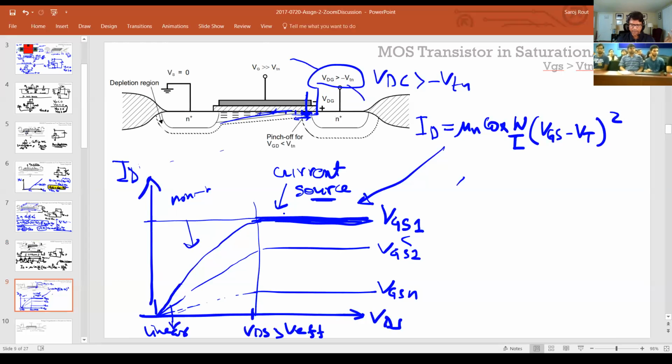So you can see that we used it as a capacitor, a linear resistor, a nonlinear resistor, and a current source. Because in IC design, you just have these transistors, you don't have the flexibility like in board design where you can get separate current sources. You just have a few minimum devices, and with that you build everything, right? So anytime you get responses like that, you have to exploit them. So this is one of the ways we exploit it.